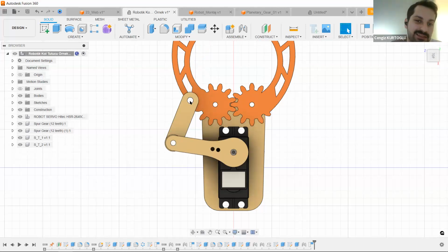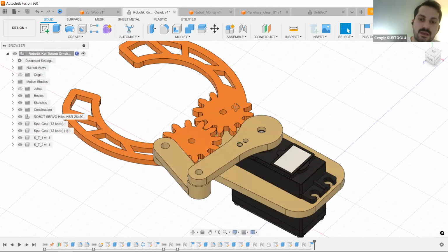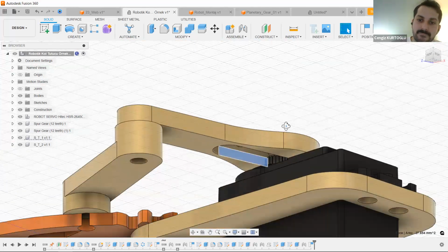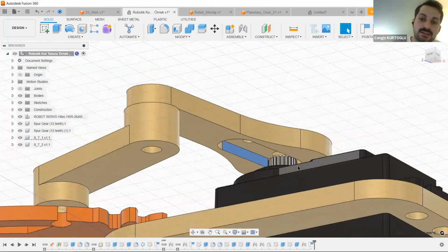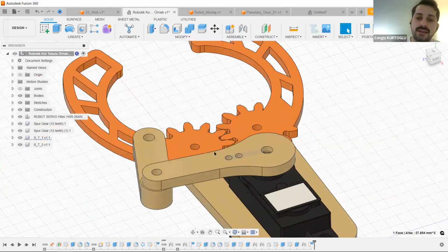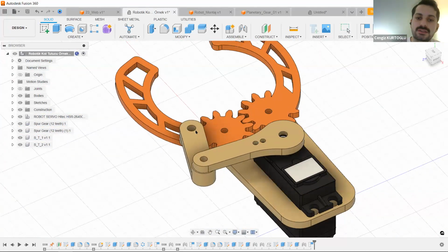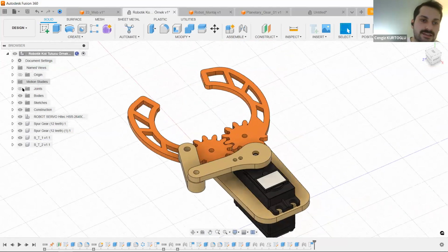It should be exactly the same spot for the 3 parts, which is quite important, because there's a key holder for the servo motor in the first part, and then there is a second part which drives the spool gears. After that, you will use the same technique to add some joints to our parts.